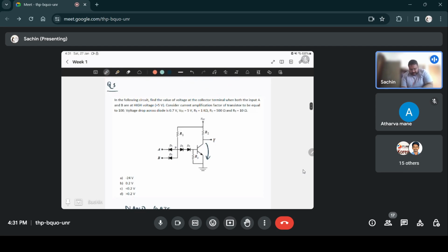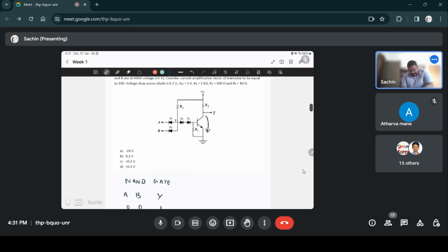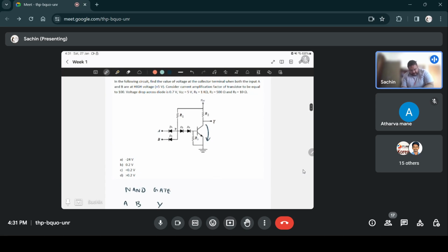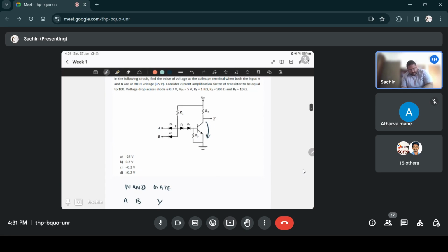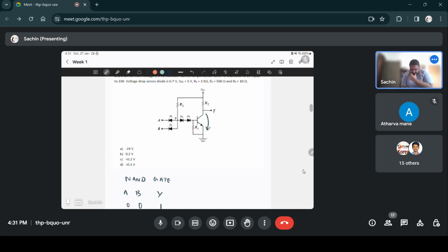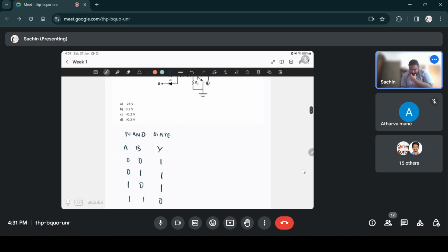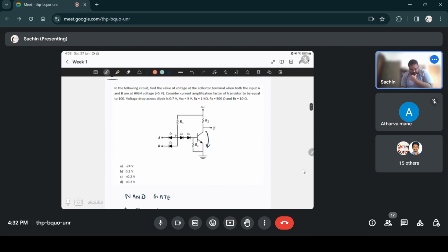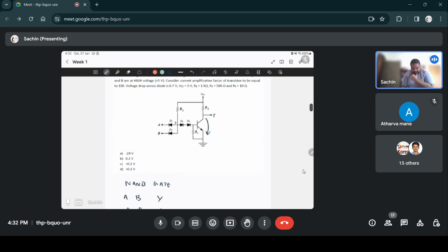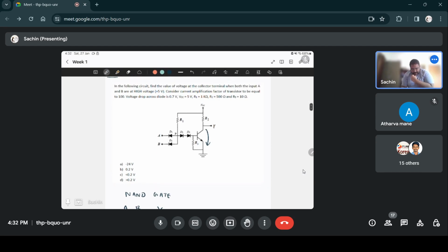For saturation, here they have assumed that it is the same as whatever was taught in the lecture, 0.2 volts, but the output will be a little less than 0.2 volts. So this is if you know exactly what operation is happening. Otherwise, you could do network analysis.